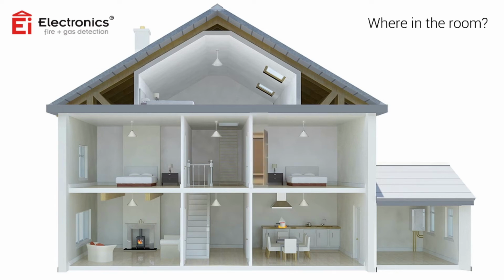Where to avoid positioning alarms? In an enclosed or obstructed space, directly above heating or cooking appliances, directly above a sink, next to doors, windows, extractor fans or air vents, in an area where the temperature exceeds -10 degrees or +40 degrees Celsius, in any contaminated or dusty environment.